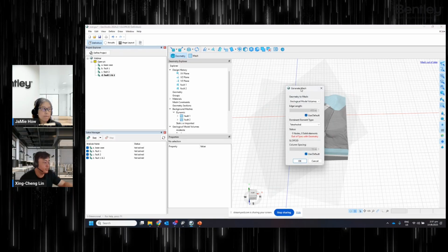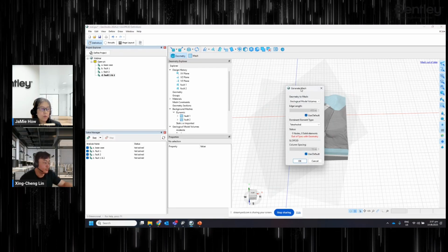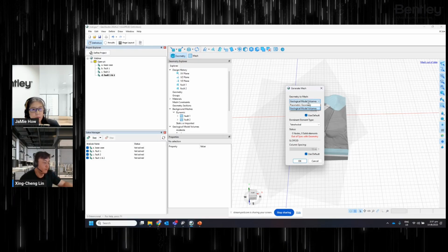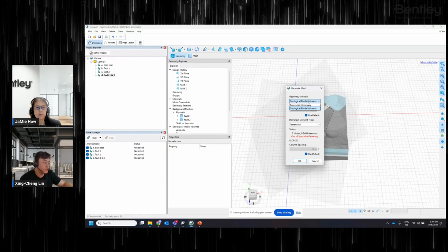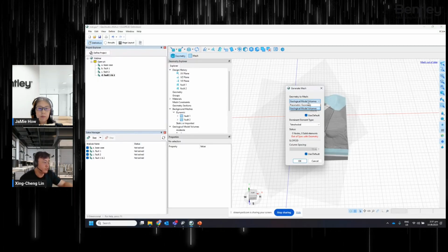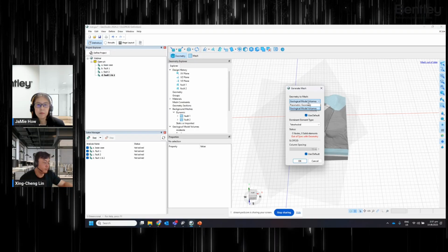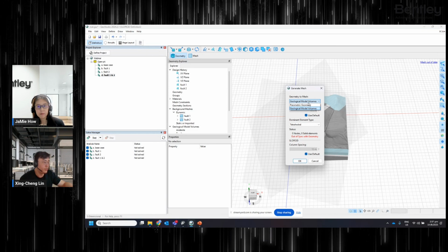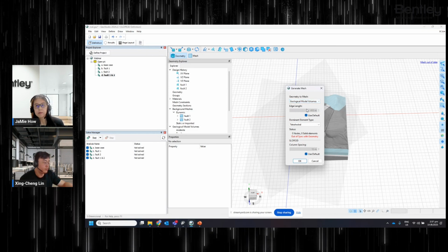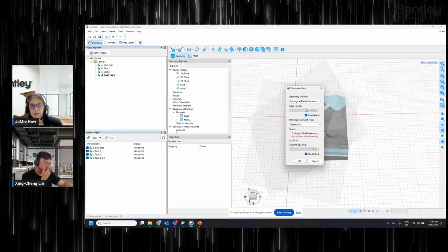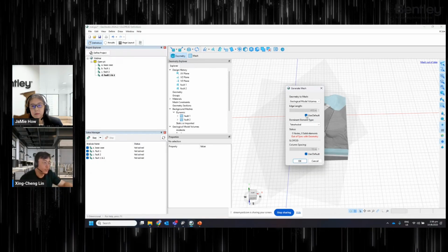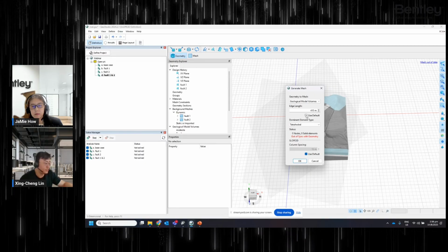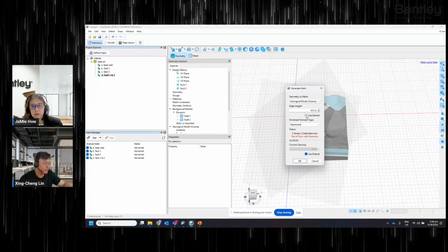We're going to hit this button. We have two options. You can mesh a geological model volume, which is what we're doing right now, or mesh parametric geometry. Parametric geometry is what you actually import from, for example, CAD packages. In this file, we only have the geological volume here, so that's our option by default. The first mesh option is for the geological model volume, and that's what allows us to visualize the contour and data on the domain.